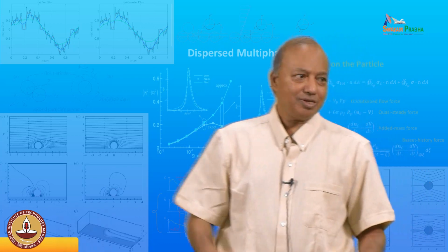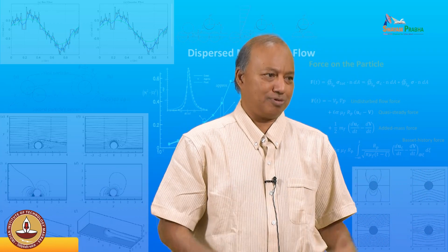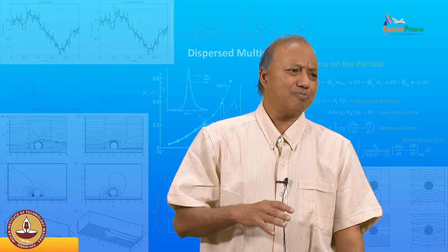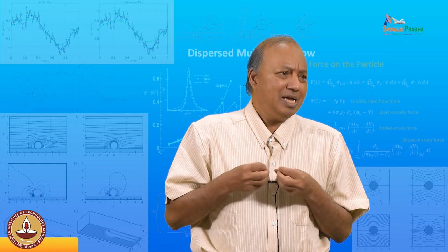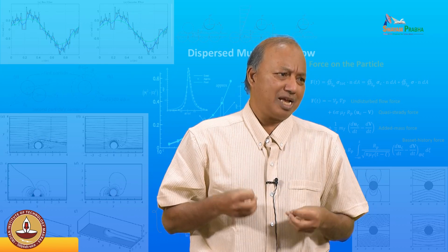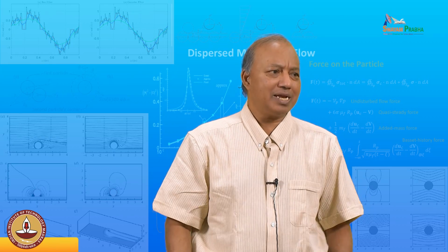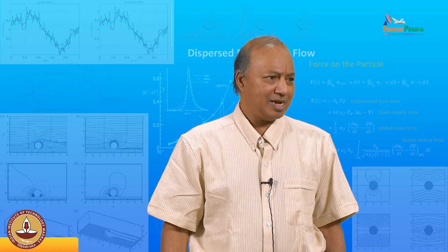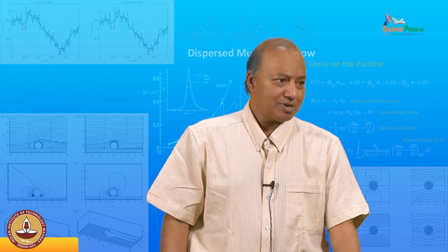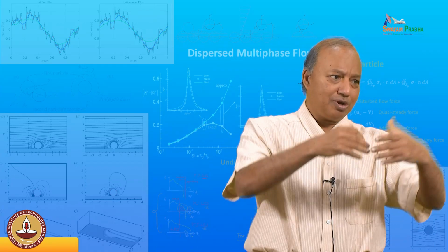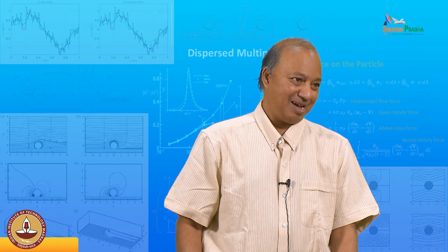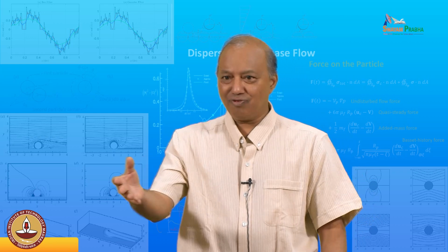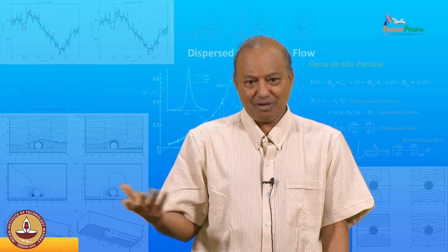Yes. Okay. So the strategy he used is a binned approach. And he also used some more sophisticated approaches, called overlapping bin structure, etc., because collision is the most expensive part. So he tried to make it as accurate and as efficient as possible. In fact, he was trying to do this for a shock going over a densely packed bed. Therefore, a lot of collisions were happening. So many of you are doing fluidized beds, and this may be a good fit.